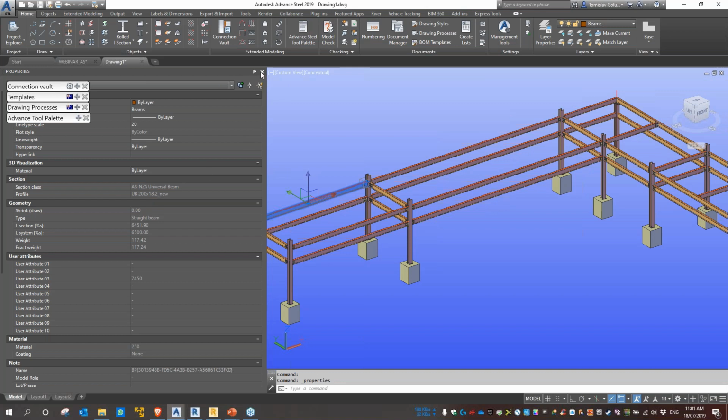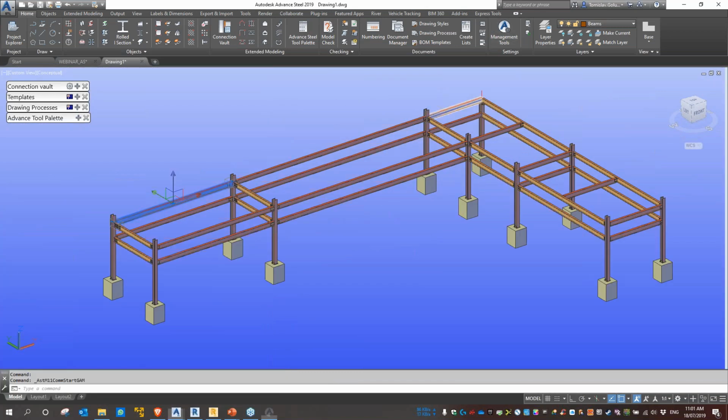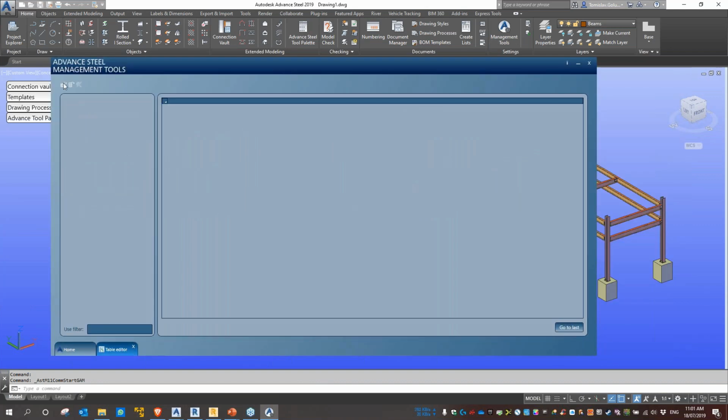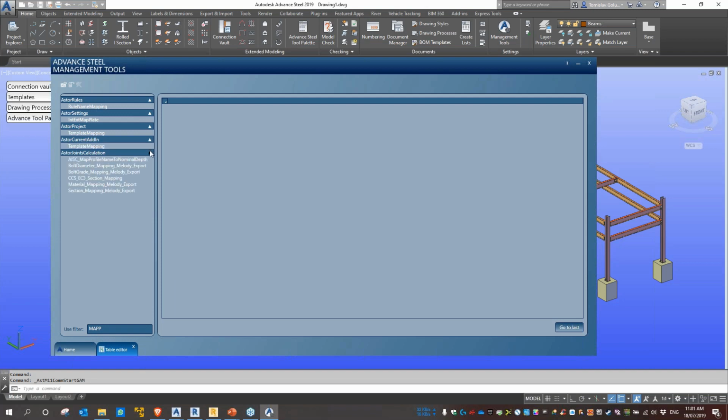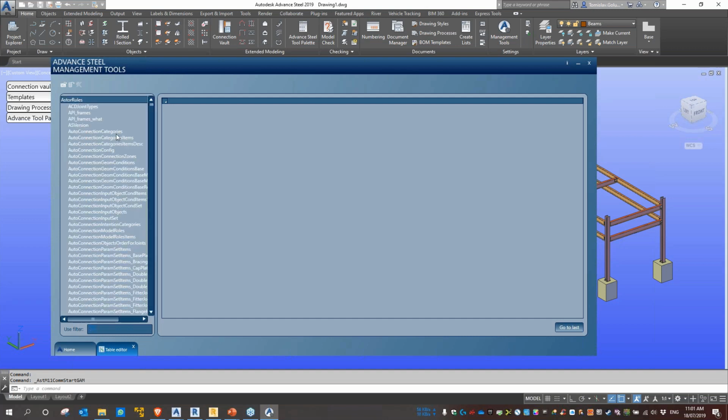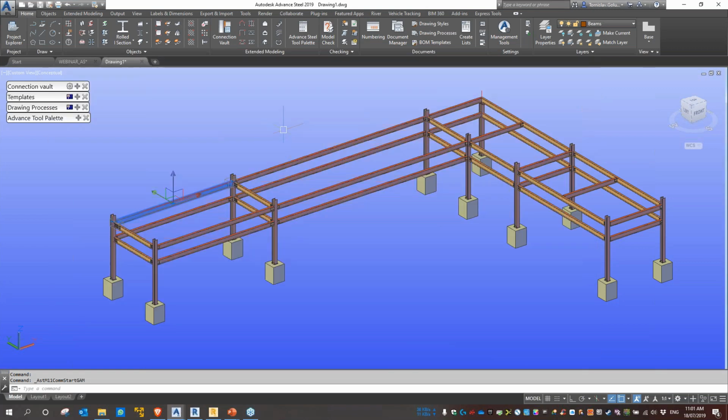Now, I probably won't delve into it too much, but under the tables, there is one called mapping. I think it's called GTC mapping. There is a database entry inside here that talks about if you're going from Revit to Advanced Steel or Plant 3D to Advanced Steel. Most of those, you can see the members that I brought in, I didn't need to do any mapping for.